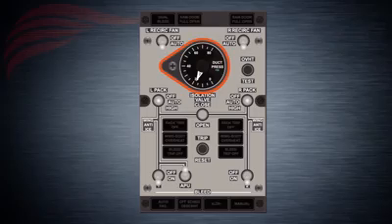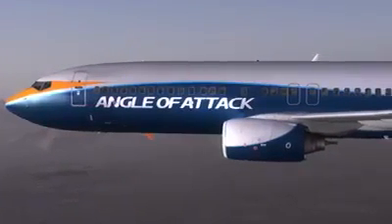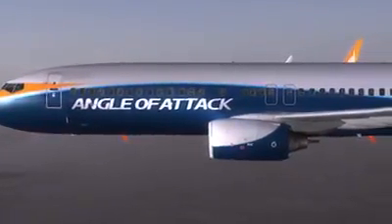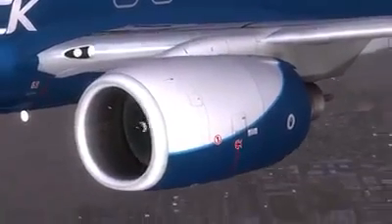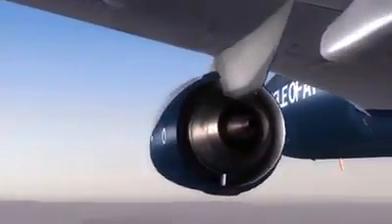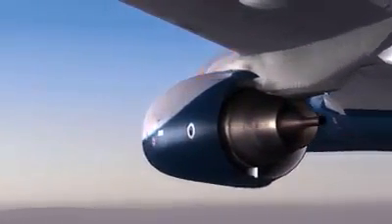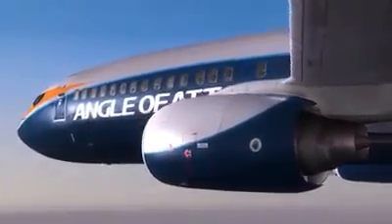Moving on, we'll now talk about each individual source of bleed air on the 737NG. Let's start with Engine 1 and 2 supplied bleed air. The engine bleed air system supplies pressurized and regulated bleed air from the 737NGX engines into the pneumatic manifold. Even though engines are very thoroughly discussed in their related lesson, we're going to briefly mention a few general aspects of how an engine works.